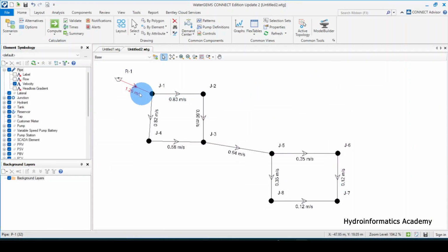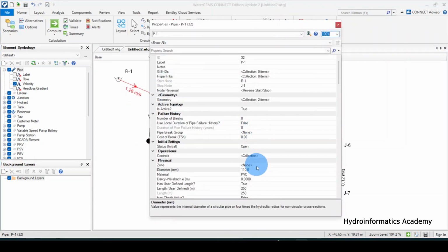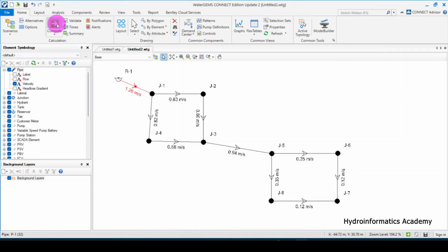You can see now we are having 0.2 and no longer 0.89. Let me increase a little bit and see what I have, 160 pipe, and see what I have. You can see now this is what we are having, 0.6. Let me maintain this one, then if there is anything that I can change, we're going to change it later on. Now the other area is of course this one here. You can see here we have very little values for velocities, but let me not touch these ones for now.